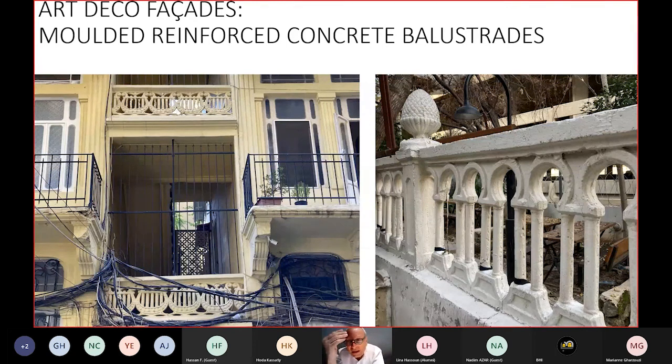They didn't know that at one point metal would rot. They didn't know at the time that the metal, once it's oxidized, would gain in volume and affect the cement by causing cracks, etc. So all the buildings at the time were built in the same material and the same technology because it was easy, efficient, time efficient, and cost efficient.